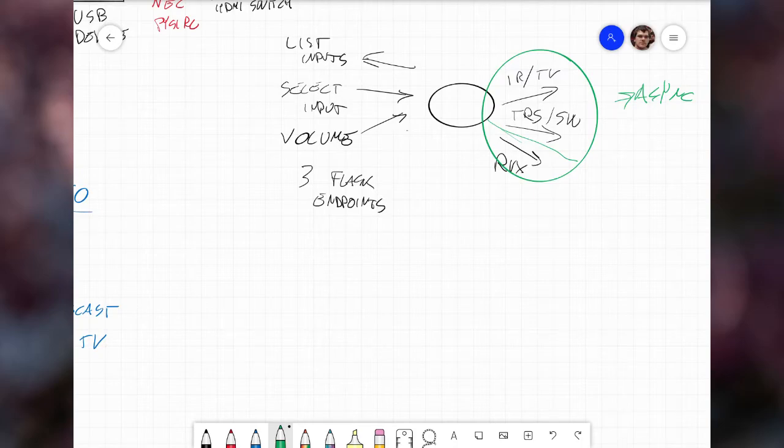Not these two in parallel, because they go through the same FT232. It doesn't actually have any smarts. It actually needs to bit bang the whole thing, which is fine. It's not high precision that you need for that one. The first pulse that you send of an NEC protocol should be 9.4 milliseconds. The remote sends 9.1, and it's still taken fine. So it's very flexible with these things. As long as the relative marks and spaces are the right shape, it will do fine. So all of these can be async, and that's not a problem.